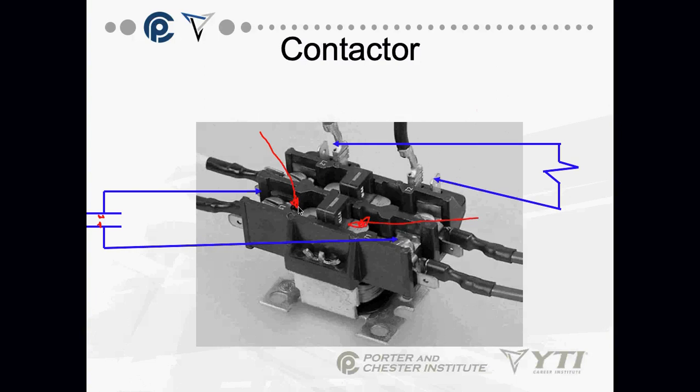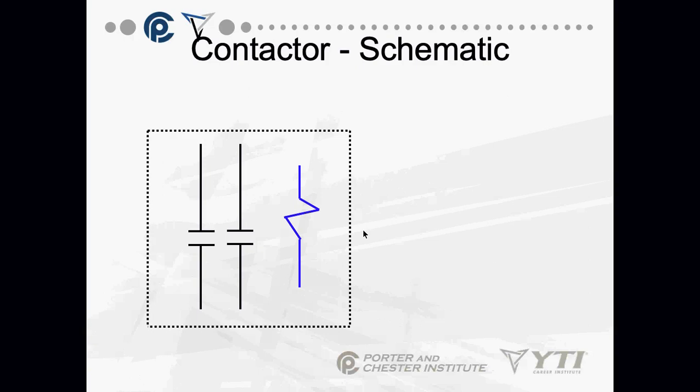Because as the electrical flow is reduced to whatever's connected to it, the amperage is going to start going up. All of a sudden I have resistance because of the carbon buildup in series with a motor or two motors. That's not a good thing because now I have a series circuit, so I'm splitting voltage. This device will start eating voltage because of that carbon. It will start producing heat, and it will just get worse and worse as time goes on.